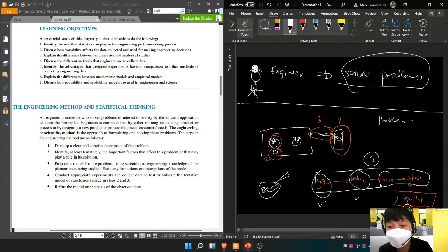And then we're going to check the hose. Is the hose properly connected to the valve and to the stove at the ends? Or does the hose have any holes? So let's say that the hose is okay. And then you're going to check the stove, the burner here. And you found out that the burner is okay. Now, the last element that you're going to inspect is the igniter.